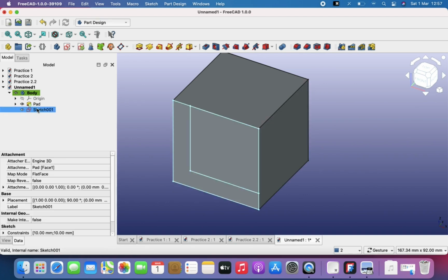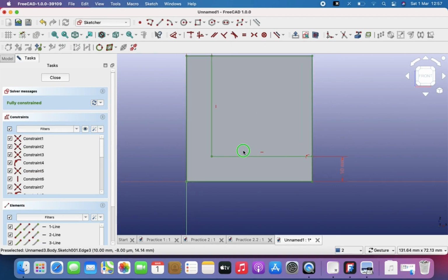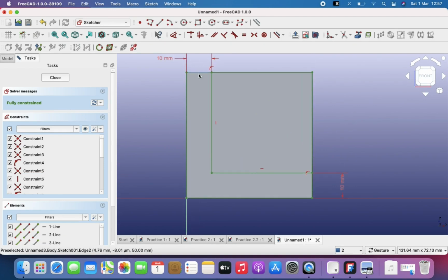So I'm going to go back to that sketch, and I have this line here. Instead of deleting it outright, I'm just going to turn them into construction lines. So I'm going to click on this and then use command. I'm going to hit command to highlight multiple lines. So I'm going to start again. Command, then click on this. I'm still holding the command, or for you on Windows, the control key, and then click on this line, this line, then this line too.